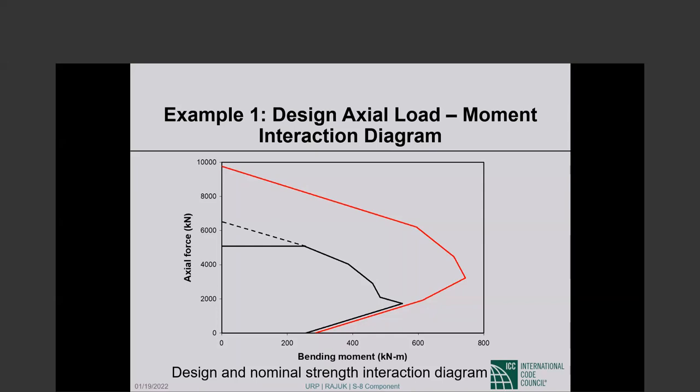Looking at all of that, we will come up with a column size, and then we will try out an amount of reinforcement based on the loads, and that is easy to do. To find a value to try is very easy to do. And then we construct for the section that we have come up with the load moment interaction diagram.